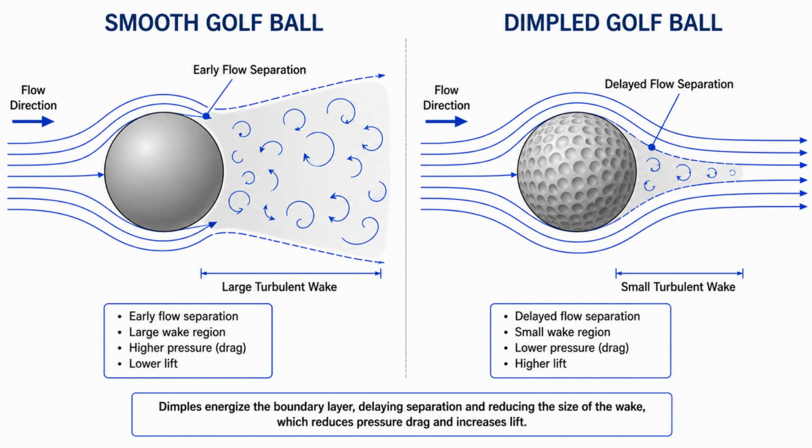So far, we've discussed how boundary layers behave around airfoils, but these same principles appear throughout engineering, and one of the best examples is the golf ball. At first glance, you might think a perfectly smooth golf ball would travel farther through the air. Surprisingly, the opposite is true. The dimples on a golf ball intentionally trip the boundary layer from laminar to turbulent. Although a turbulent boundary layer creates slightly more skin friction drag, it carries more energy close to the surface. This extra energy allows the airflow to remain attached to the golf ball for a longer distance before separating.